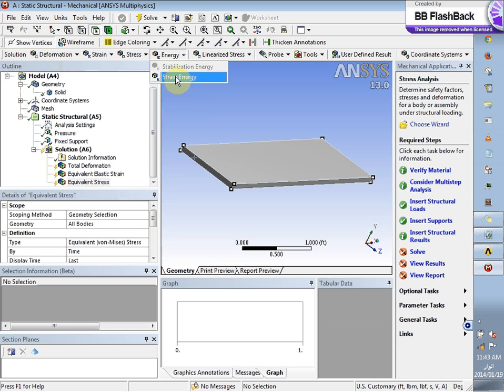So it is only strain energy. It is not plus heat energy, but plus chemical, plus sound energy, which are all produced in cracking. The total energy was the sum of all these, but when you look at the strain energy, it will tell us only wherever it is cracking. So we will know the reduction in strain energy, and wherever it is reduced, it has been cracked there. It is a tricky way to find out where the crack has appeared.